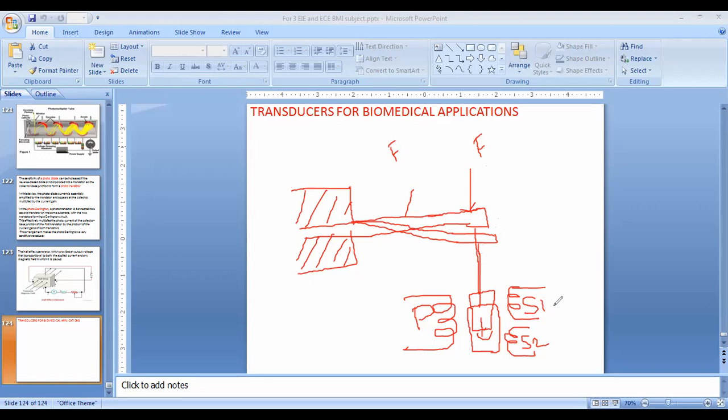The output at the LVDT is proportional to the amount of displacement applied, and that displacement change corresponds to the amount of the applied force, which leads to determination of the applied force by using the electrical signals from the LVDT. The output voltage is calibrated in terms of the applied force.